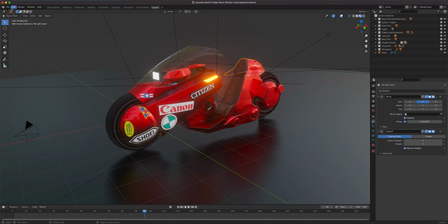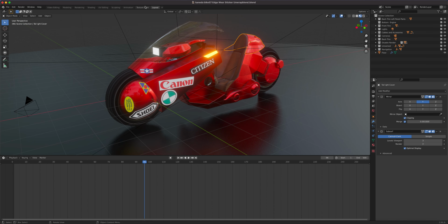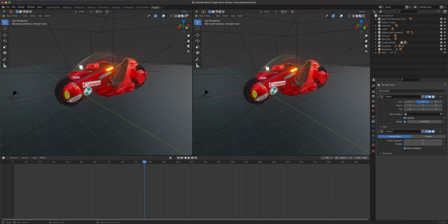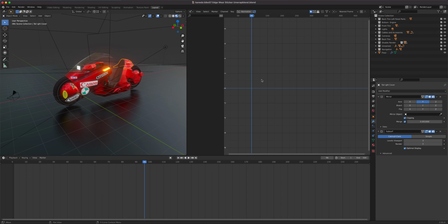Okay, moving on from the menu bar will be your workspaces. So in previous versions of Blender, all this would be just a single window, and you ended up customizing Blender one at a time, so you would adjust this. And then I'm in layout, by the way, so I'm customizing it, and then I can drag a section right there. Then I can change this to, let's say, my graph editor when I'm animating, so on and so forth. So you would customize it like this.